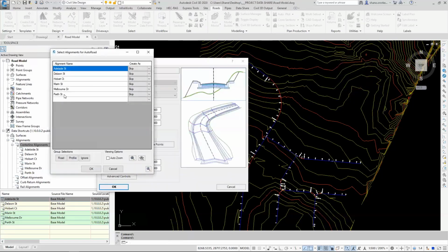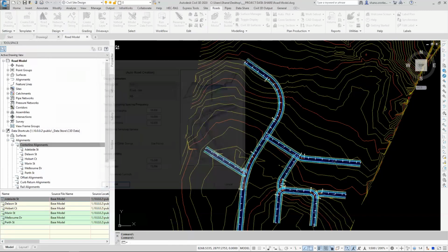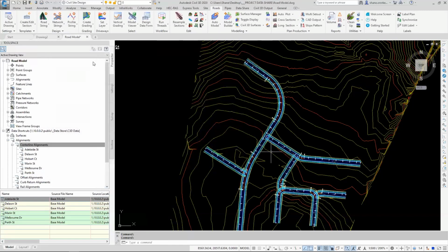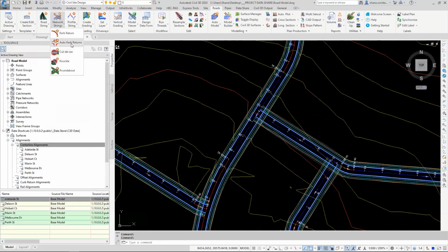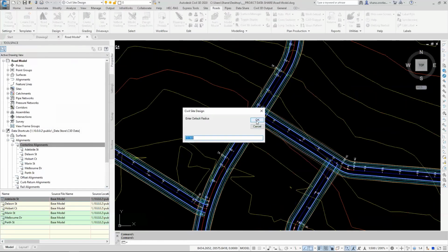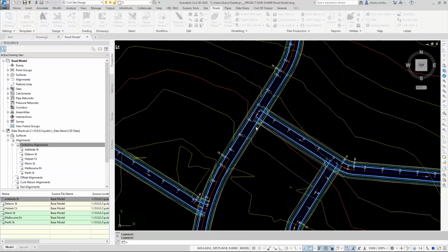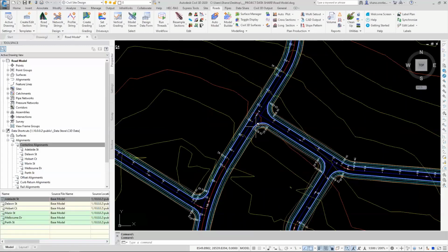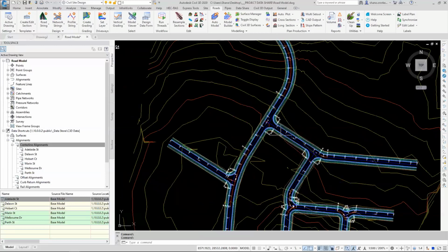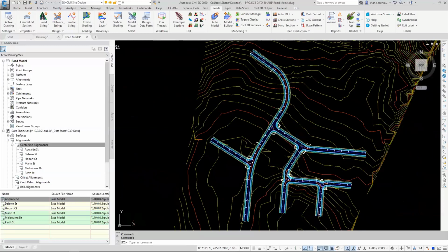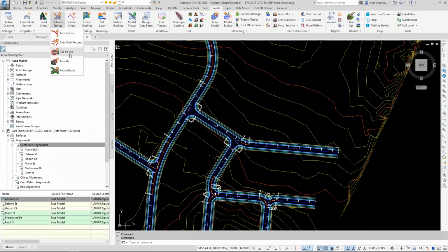So I'm just saying that all of those are roads, and that this auto create tool will make all those roads with the intersections. They're going to sweep through and create all the curb returns at once. Now we know that we can go to each curb return and individually address them, change the dimensions and behaviors, but I'm just quickly ramping out some sort of design, and I'm also going to create a cul-de-sac,